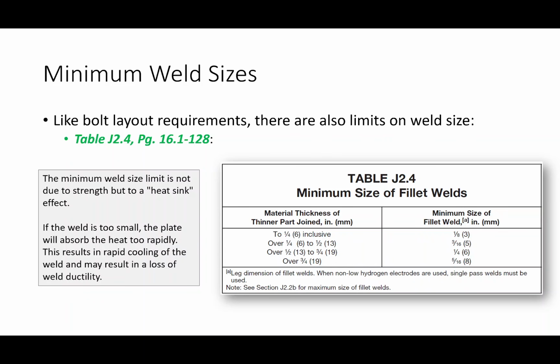The issue is essentially what I'm calling the heat sink phenomenon, okay? So what happens when you place a weld? Remember, you have part A and part B. They're clamped together. You have one end of your weld machine clamped to the workpiece, and when you connect the electrode, you complete the circuit, and energy starts to flow. So if you have this really, really thick plate of steel and you complete the circuit and begin to deposit your weld, energy starts to flow.